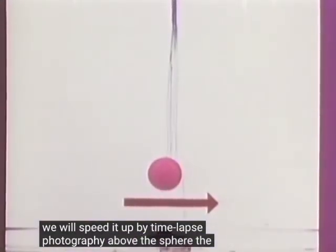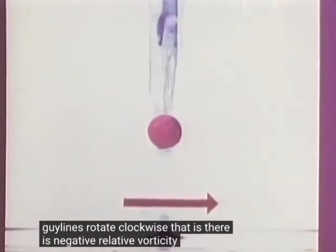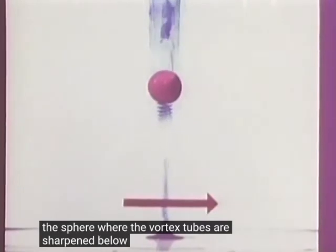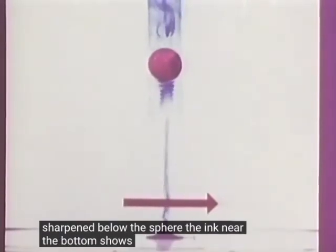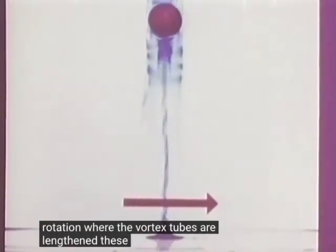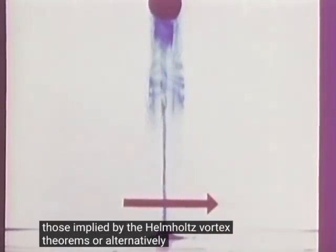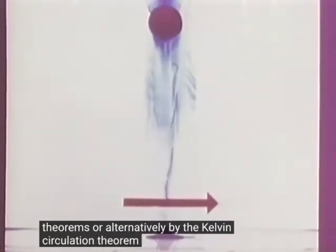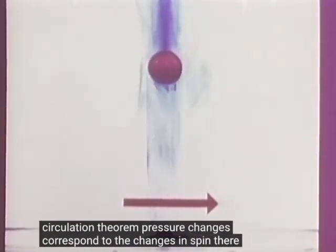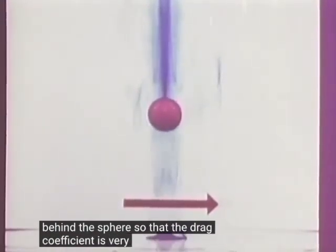Above the sphere, the dye lines rotate clockwise. That is, there is negative relative vorticity above the sphere, where the vortex tubes are shortened. Below the sphere, the ink near the bottom shows counterclockwise rotation, where the vortex tubes are lengthened. These changes in spin are those implied by the Helmholtz vortex theorems, or alternatively, by the Kelvin circulation theorem. Pressure changes correspond to the changes in spin. There is an increase ahead and a decrease behind the sphere, so that the drag coefficient is very much increased.